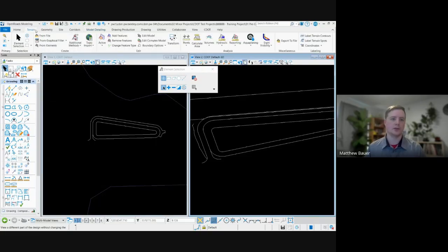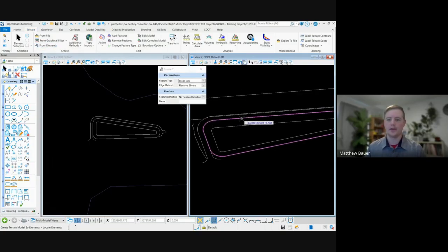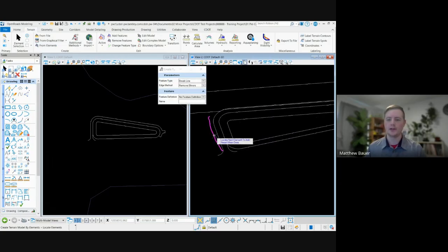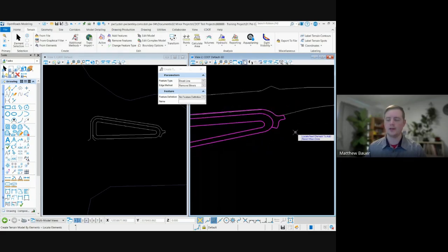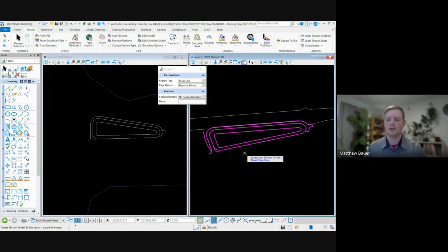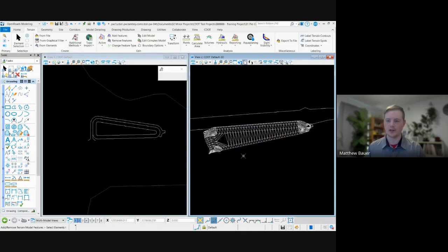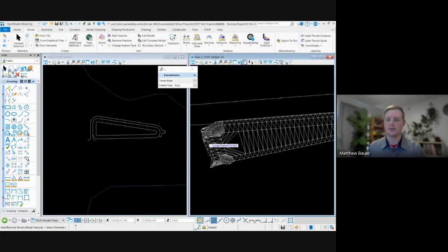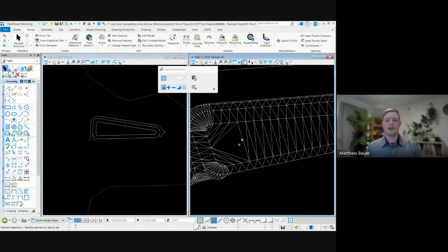So that's the last tool I'll show here. If we go back to our terrain, we can use the same from elements tool as we used before. We'll locate our elements. I want this 3D feature I drew, and I would like all my break lines to actually grade out this pond. So I'll reset when done. It's all break lines. Remove slivers works great. And now it's dropped in. Now I have a kind of odd shape, something that doesn't make sense to actually model in a corridor. And just as easy as that,